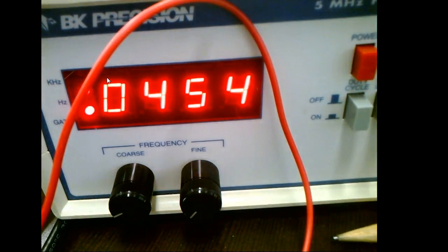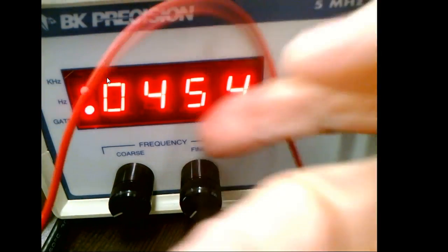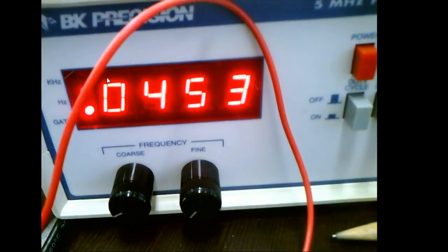So if I measured Alabama Power, our cycles would be 16.66 milliseconds. If I took the reciprocal of that, it would give me 60, right? You understand? So if I wanted to measure the frequency, I would use a frequency counter. If I wanted to get a good idea of what the frequency was, I could use an oscilloscope. And an oscilloscope's going to get you close enough so you know if it's right or wrong.